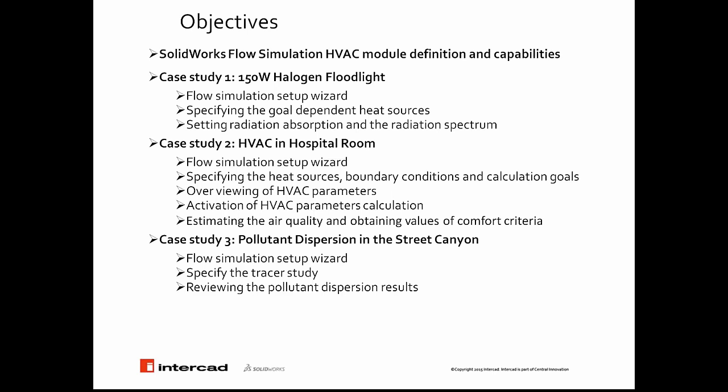The first case study is a 150 watts halogen floodlight. We will learn how we set up a project in Flow Simulation, and a specific highlight in this case study is how we can make goal dependent heat sources, and also how we set the radiation absorption and radiation spectrum.